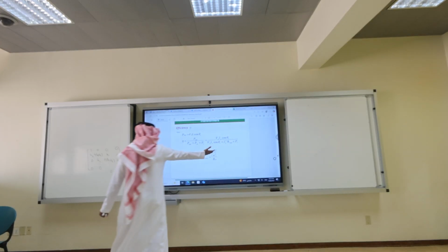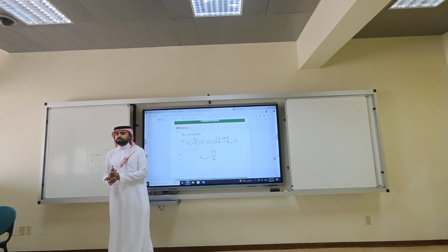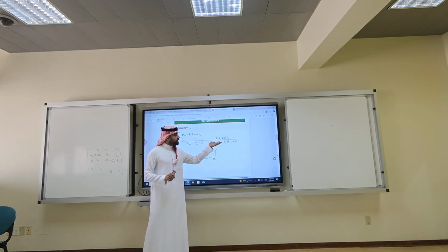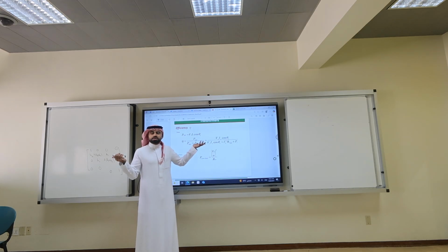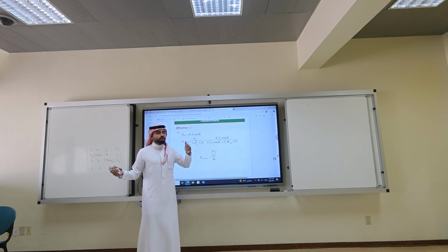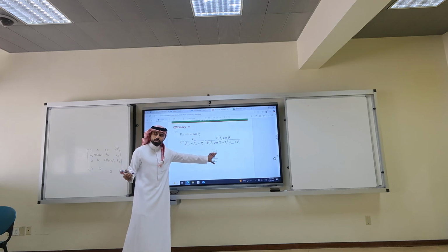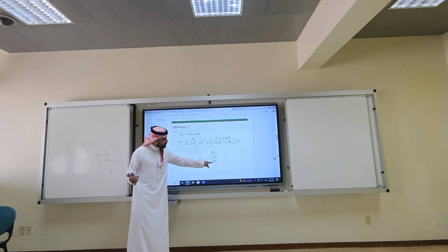This efficiency example, does it use the circuit reflected to the primary or the secondary? Secondary. Why? Because I don't have V_S prime. So you can use this equation directly. Again, is it useful to memorize the efficiency equation? No, because I don't know which circuit I'm going to have. Maybe circuit 3, maybe circuit 1, maybe circuit 2. So this one is for circuit 2, referred to secondary. This one is V_P squared over a squared over R. You can call this just R_C.